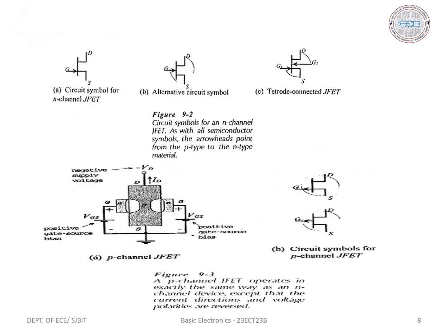Next we have a P-channel JFET. This is the P-channel JFET characteristics. The figure shows the characteristics of a P-channel JFET. The difference in the arrowhead of the gate and the direction of drain current can be seen in the circuit, and also the polarity of the supply. The drain is negative with respect to the source and the gate is positive with respect to the source.